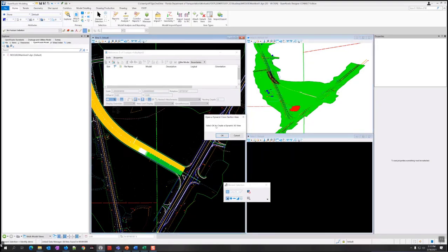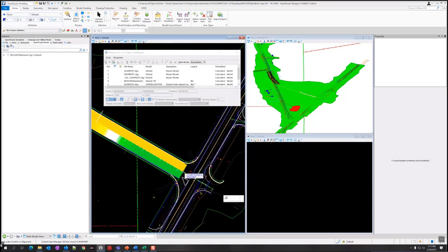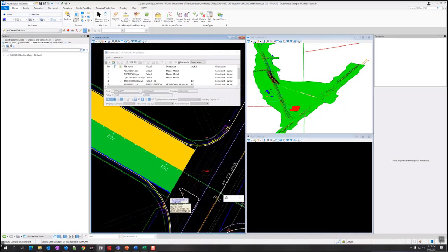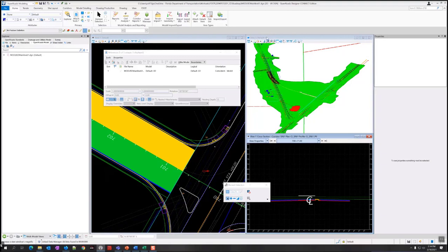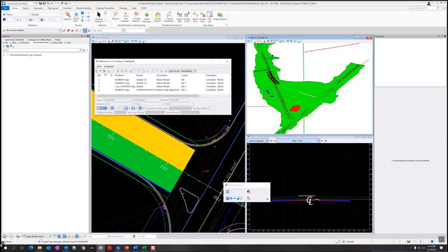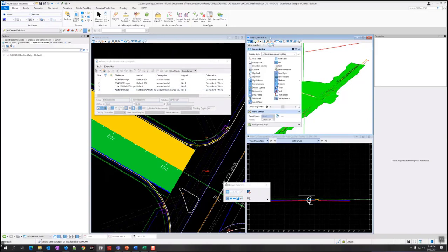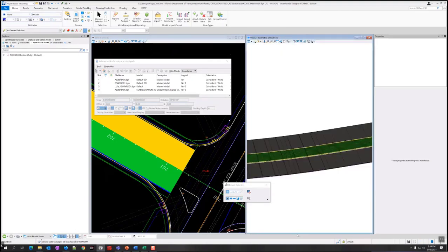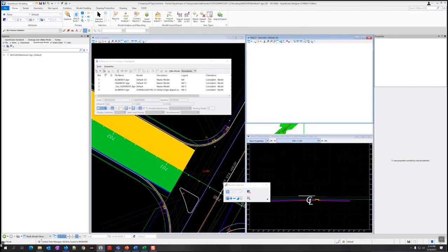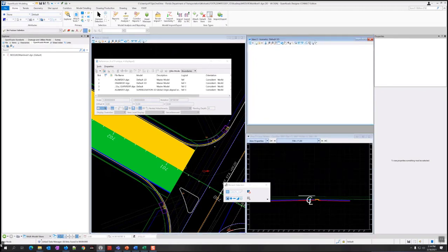It asks me to select OK to create a dynamic cross-section view, so I click OK, and I want to pick the corridor. So let me just set these short corridor handles, and then select over here in view 7, and open the view there. Now we still, I think, have an issue with that view control in that it changes the view over here. Change it from view 2 to view 3. So let me just close out view 3 and go back to view 2 because it's already set up.